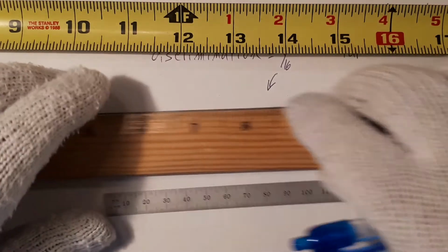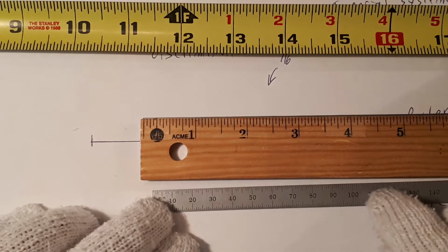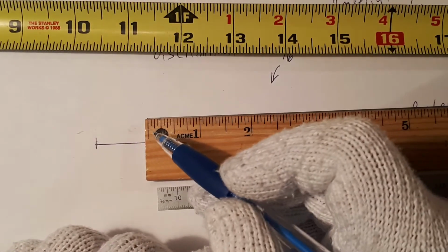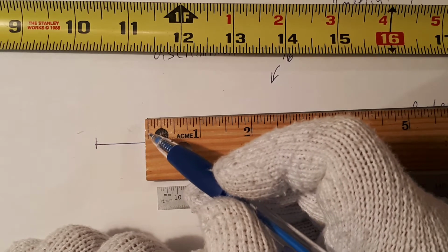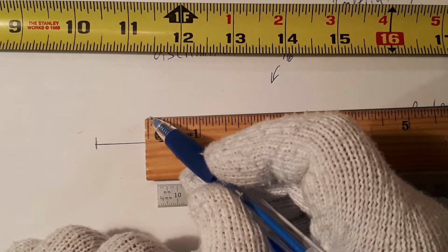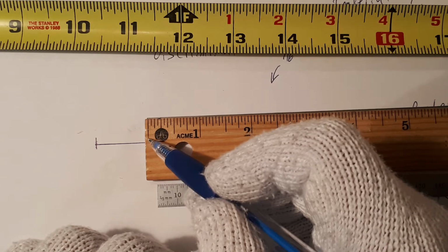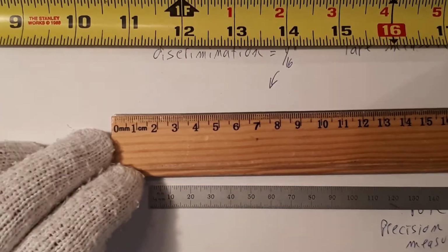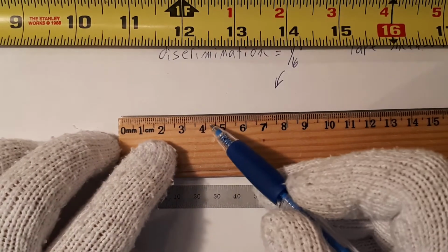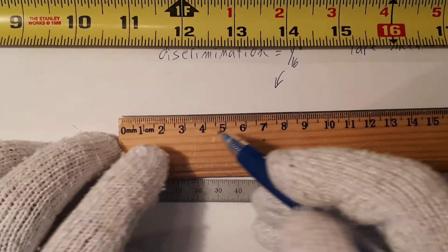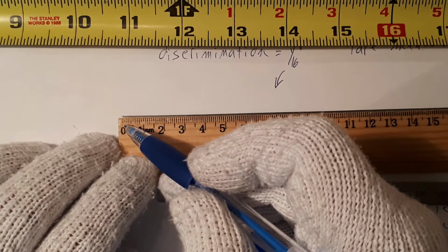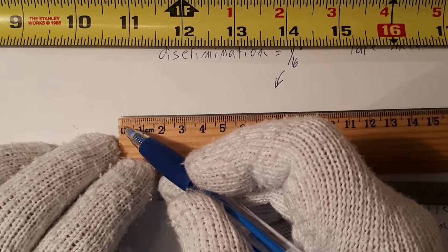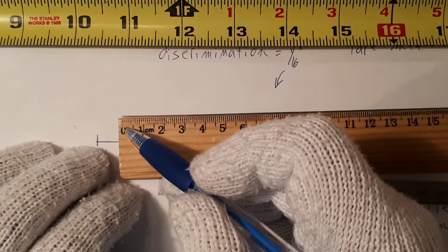The other thing about the ruler and the steel rule: on the ruler, the zero starts here. There's a little bit of wood here, and the zero starts on the inside. That'll be the zero mark. And if you look over to the other side, this is graduated in millimeters also. So each one of these graduations here is 1 millimeter. And you'll note the zero starts here and has a little bit of wood here, so the zero is moved inward.